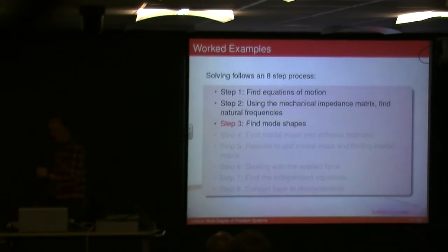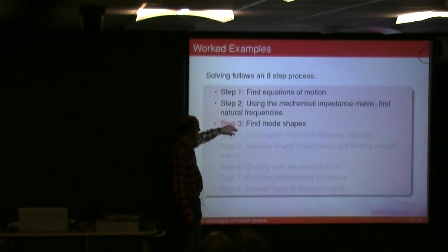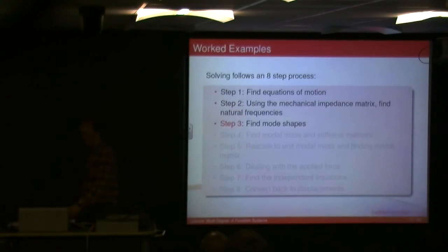Now, like I said, often you would use a computer program, like that eig function in MATLAB, to find those things, okay? And in some of the questions that we've gone through, I've actually given you things like, if you look at the end of the chapter, let's look at, for example, question 6, I've given you the natural frequencies, and I've not given you the mode shapes, but I've given you the modal masses, okay? And you'll see that there's variations on the theme, but basically, that's the process you go through. And for the 2-degree of freedom system, it's fine. 3, it becomes a bit more difficult, and 4, like I said, you wouldn't be expected to solve something like that by hand.